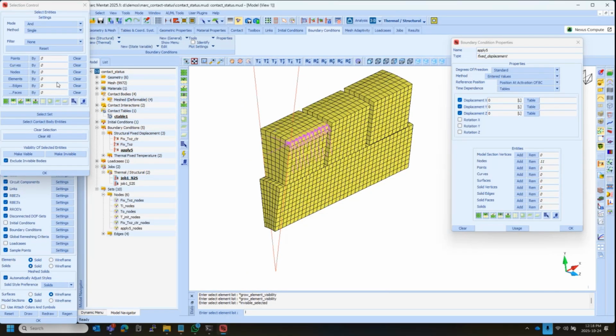Okay, now another feature that's useful there is, so this is how we pick, but the first one is what do you want to do? So let's say I do a flood, just to make it easier. I select these and these. Those, and then I realize, but I don't want certain ones selected. So I can switch it back to single and say accept, and I pick a couple of elements and it removes that from the list. Just remember to switch that back to and, otherwise you clear the list and everything you select is not added.